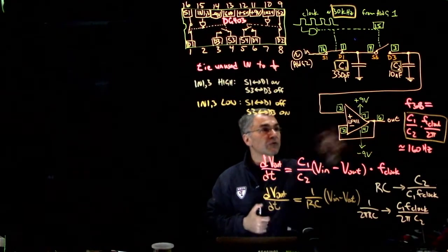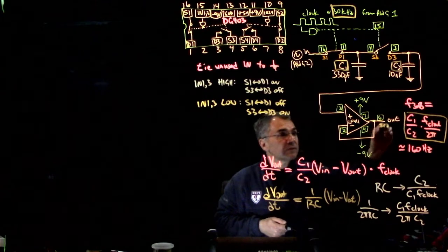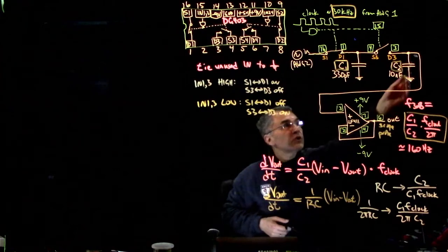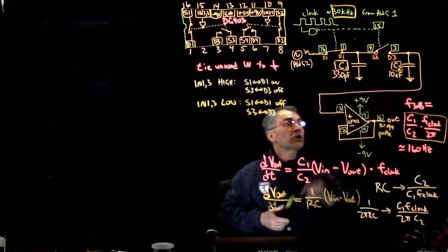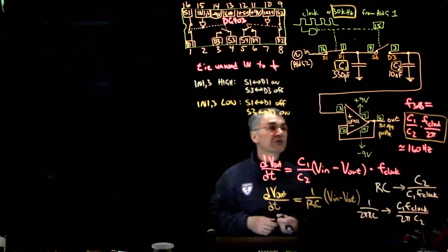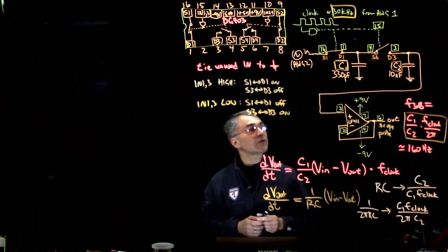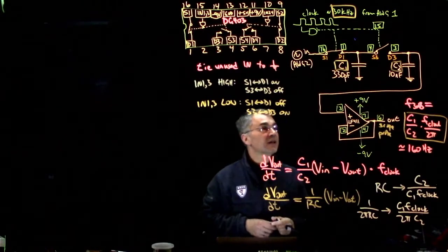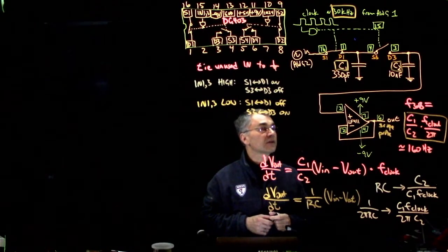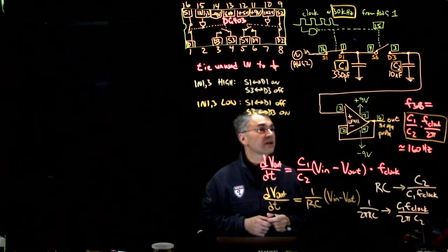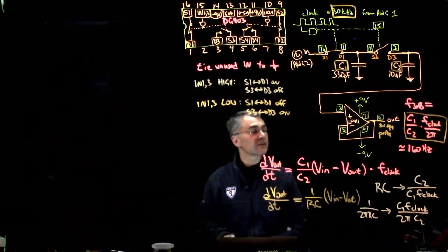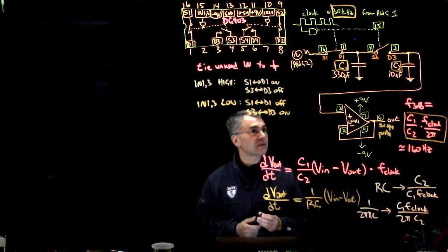So then we can observe this with the scope probe. If we plug the scope probe directly over here, then that's 10 megaohms input resistance, and it would drain the charge off this capacitor relatively quickly. Well, how quickly? I guess we could say the RC time constant would be 10 nanofarads times 10 megaohms, which I think is 100 milliseconds. I don't know if we want to pause to do that. I think it would be 100 milliseconds.